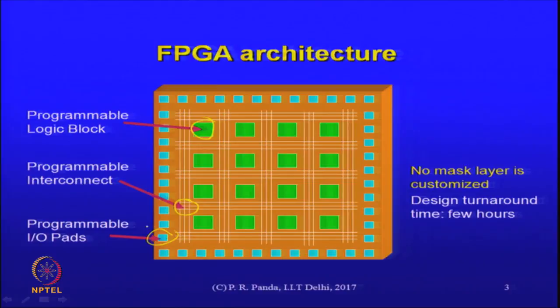Can it reconfigure at runtime? Yes, this partial reconfigurability is a feature in modern FPGAs. You can do it. So, essentially what reconfigure means is that the configurations also have to be dynamically accessible somehow. So, for some time you run it on one configuration, and in later stages you can run it on a different configuration. Modern FPGAs do have that facility.